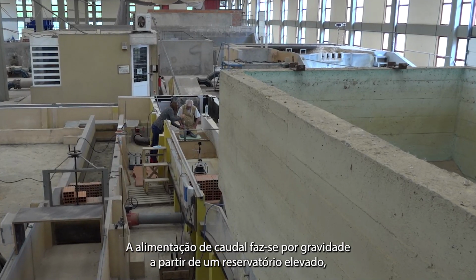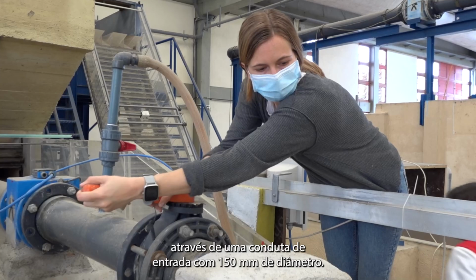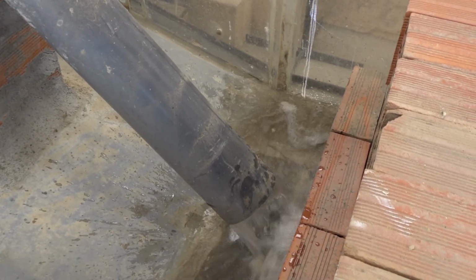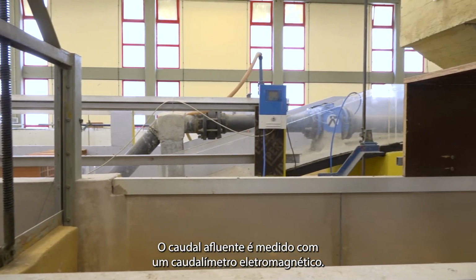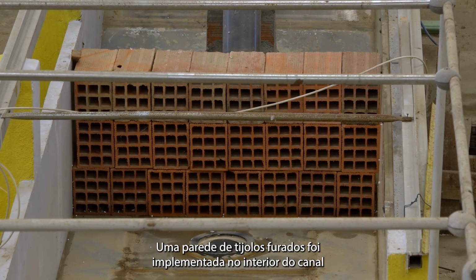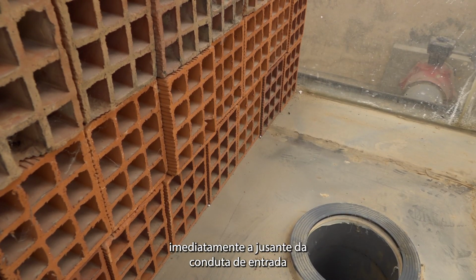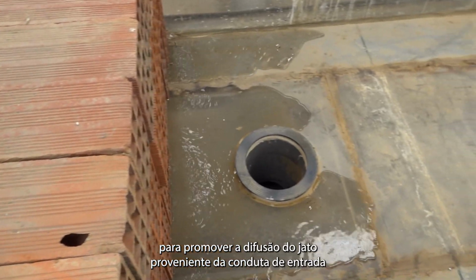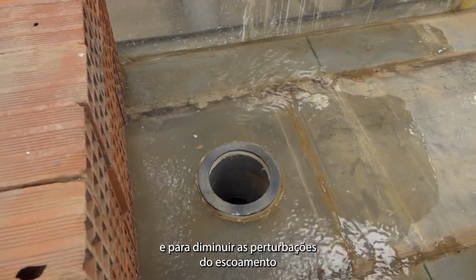Water is introduced by gravity from an upstream reservoir through a 150 mm diameter inlet pipe. The discharge is measured with an electromagnetic flow meter. A pervious brick wall is installed inside the channel, immediately downstream the pipe exit, to diffuse the jet that flows out of the inlet pipe and to quiet the flow disturbances.